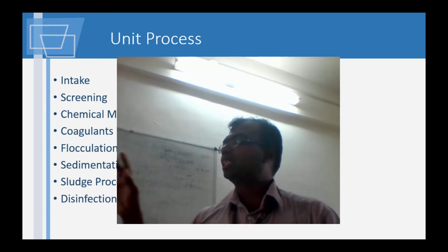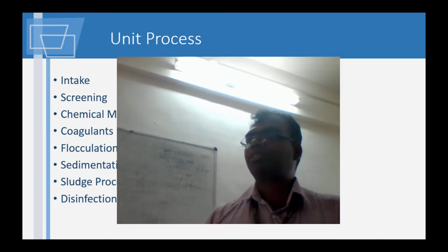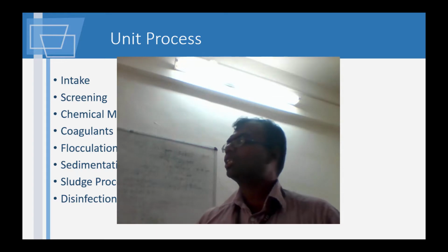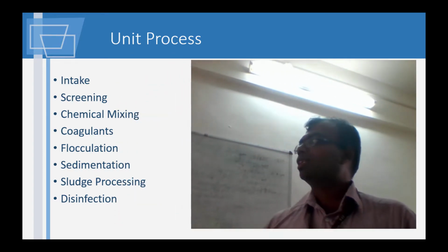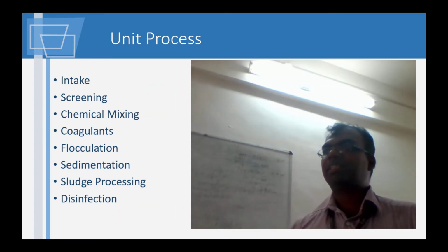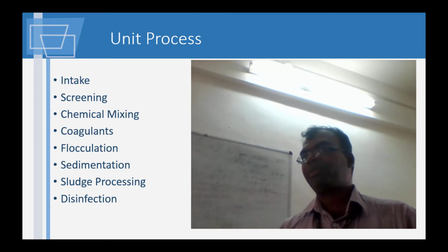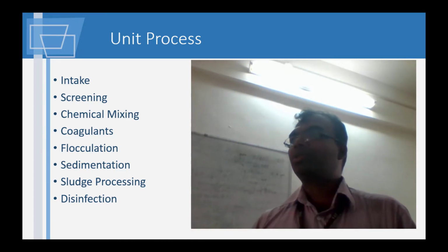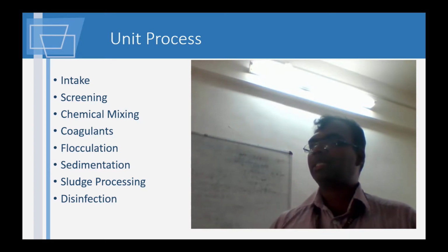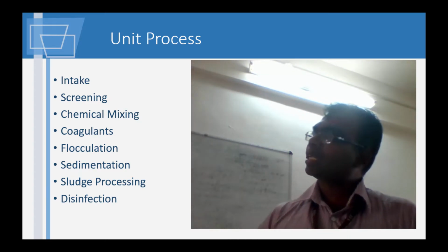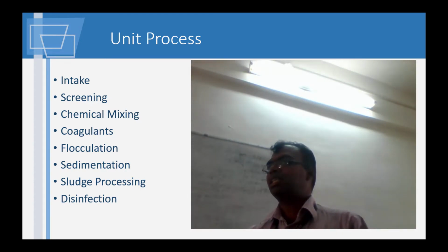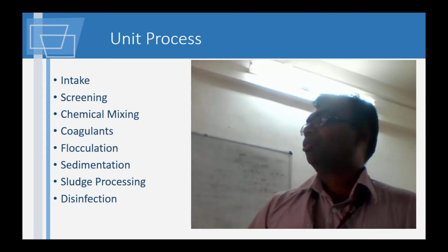In almost all the videos you would have seen the screening operation. There are different types of screens: bar screens, rotating screens, and so on, because each type of screen will require frequent cleaning. So the next time you go through the videos in the presentation, please note the way they show it. Yes, they are mechanically cleaned, automatically cleaned. You cannot be manually cleaning the screen every time, not at that rate of flow.